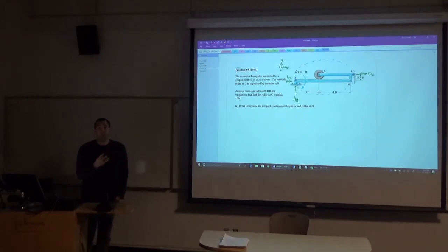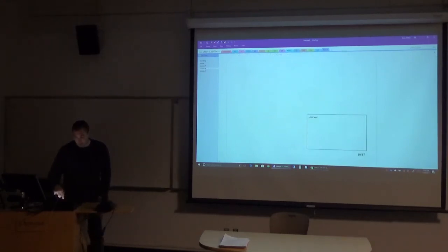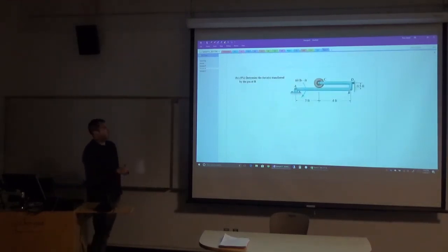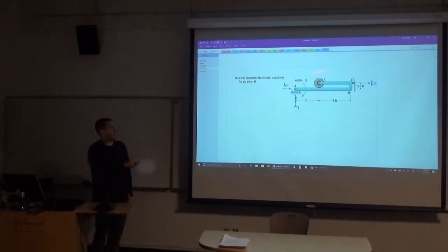Which is great. But is that going to get me the answer to part A? Part of the way, right? Actually, I'm sorry, for part A, it's going to get me all of those reactions. Now, part B is where we can't rely on the global free body diagram, and we need to start looking inside. In part A, the global free body diagram has gotten me the vertical reaction and the horizontal reaction, both at the pin at A and at the roller at D. So the global free body diagram was enough for part A. Part B is trickier.